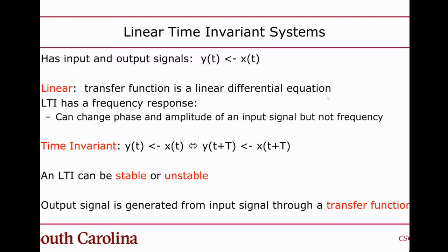They also have a frequency response. You'll see this a lot. We're not going to be talking much about frequency response in this class, but you're familiar with frequency response from Electrical Engineering 222. If you have one of these LTIs, you can characterize its frequency response. Its output will always have the same frequency as its input, but you'll get a different phase and amplitude depending on the input frequency.